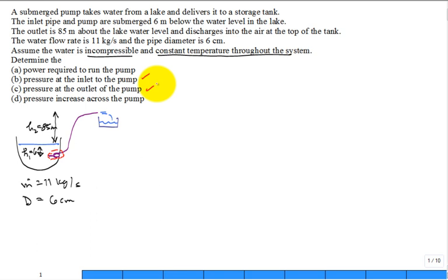So a lot of people say, it really doesn't, I'm going to try and change color to green here, really matter where you cut it in the air, because there's no water cutting across the boundary of the control volume in the air. So it really doesn't matter if I have a box or just follow closely the pipe.